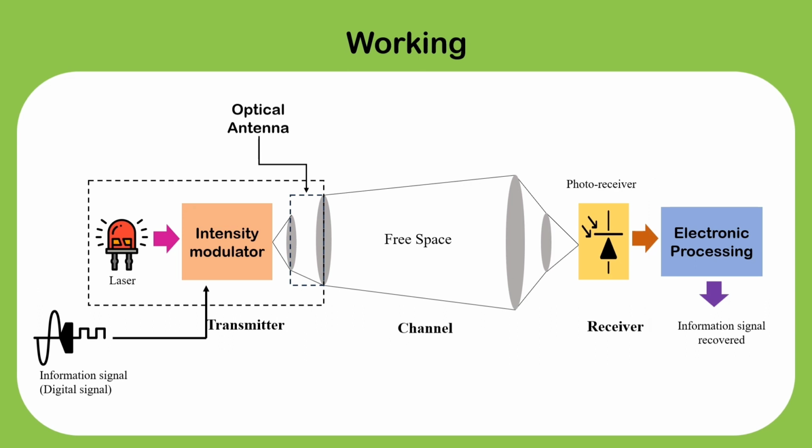One of the most important things is that the transmission aperture must be properly aligned with the receiver aperture, so that the light intensity after propagating through the free space can be captured by the photodiode directly. Therefore, free space optical communication system is preferably a line-of-sight communication. In order to ensure the alignment, a system known as positioning and tracking is used at transmitter as well as receiver side. The performance of the FSO system will degrade with the misalignment of the transmitter and receiver.